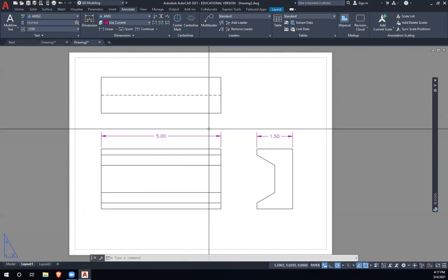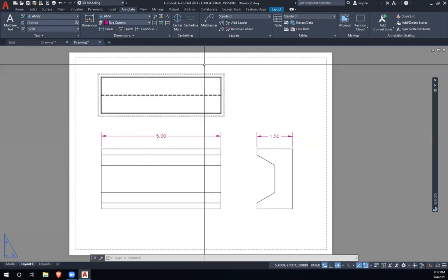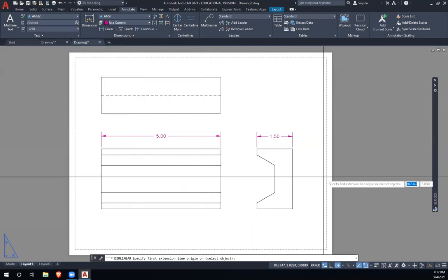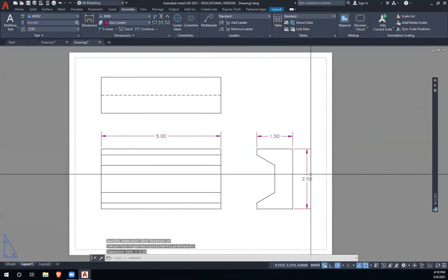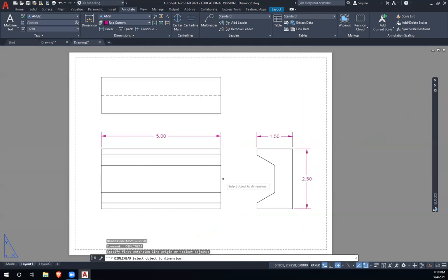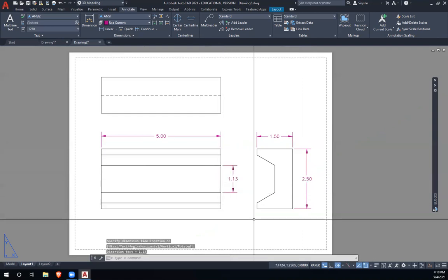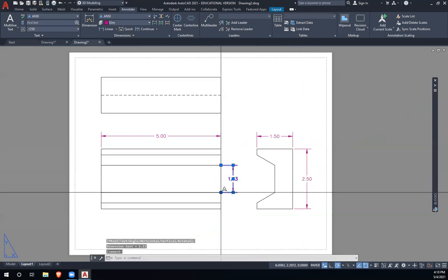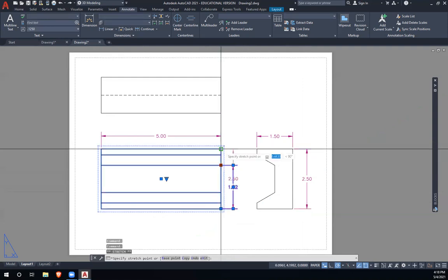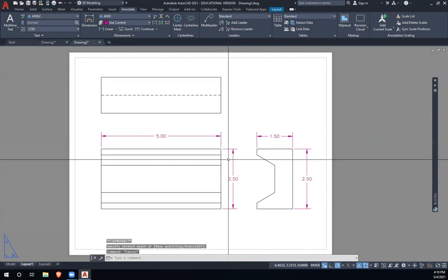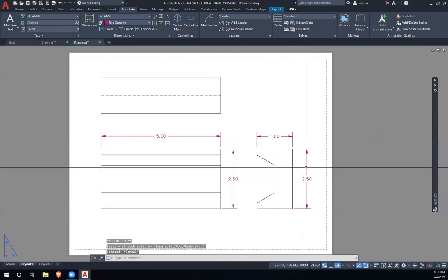So it still keeps the basic size of the drawing kind of the same, but now I can add more detail without making it bigger. So in other words, I wouldn't want to put this dimension over here. I'd rather put it right here. Yeah. Let's make that bigger. There you go. So it's much better in between the views than out here all by itself.